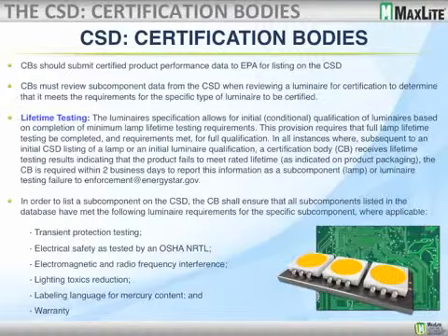Once you've got your product on the CSD list, a luminaire manufacturer can go to that list to get that information. Now, lifetime data, because particularly with LEDs, lifetime can be very long on these products. In some cases, in past programs, the testing procedure for verifying lifetime was longer than the marketability life cycle of the product. So it was a big problem. So what the CSD has done today for lifetime testing is the luminaire's specifications allow for an initial qualification, a conditional initial qualification based on the completion of a minimum lamp life testing requirements.